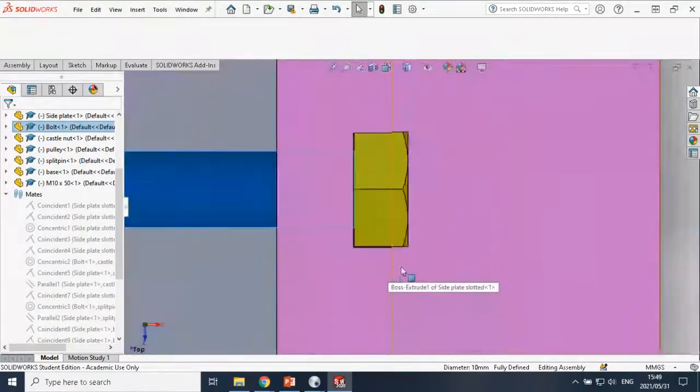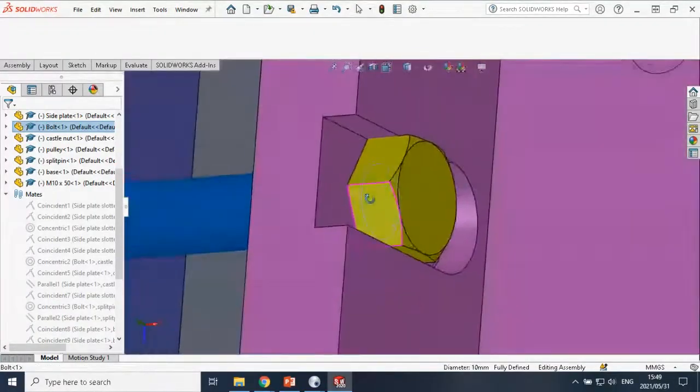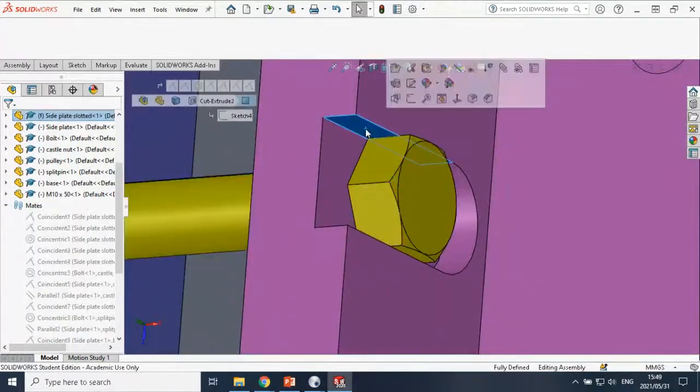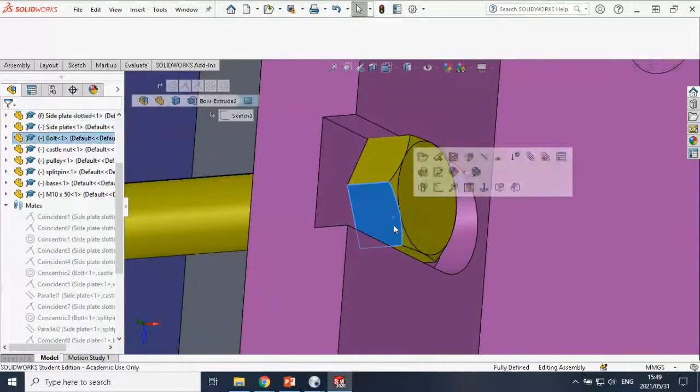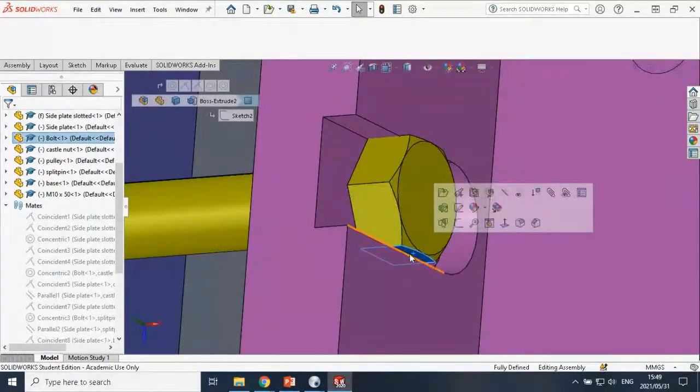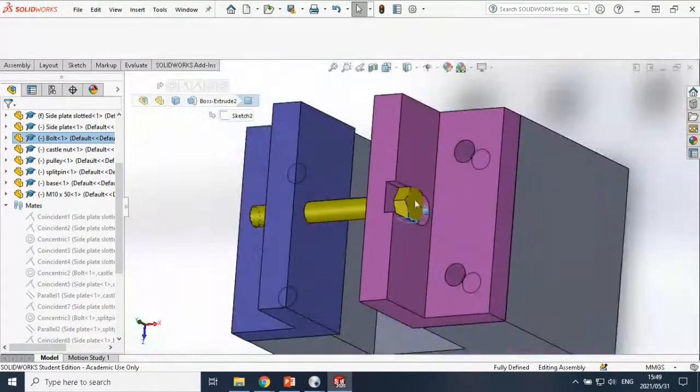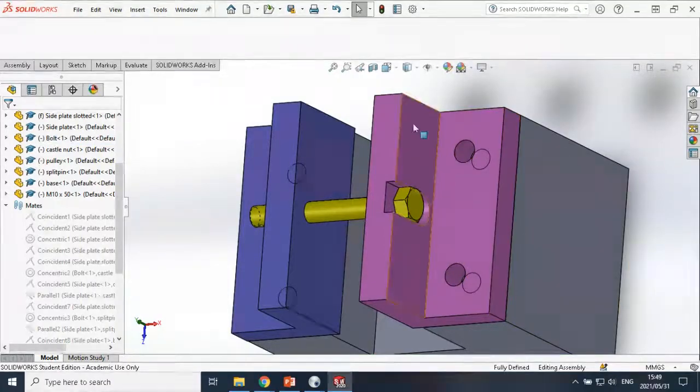So basically what's going to happen is these sides will stop that bolt head from being able to rotate because it keeps that flat plane and the one on the other side stationary, so it holds it in place. So this is almost like a locking device that's built into a part.